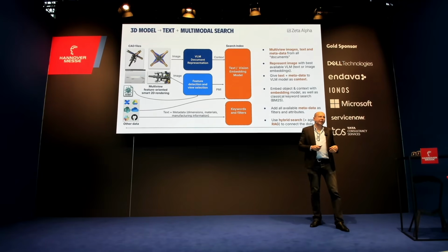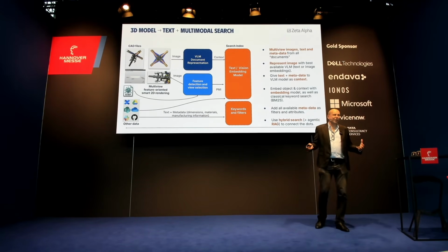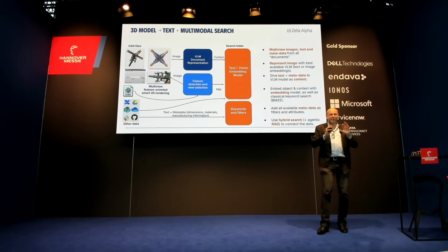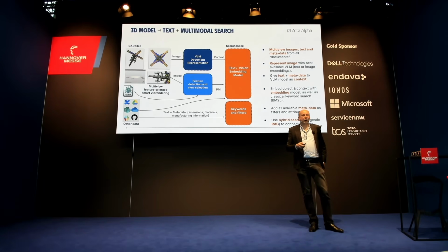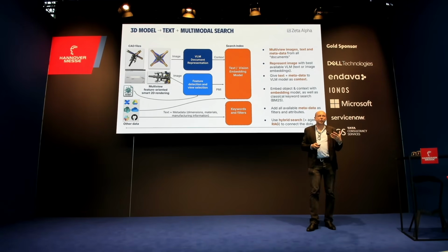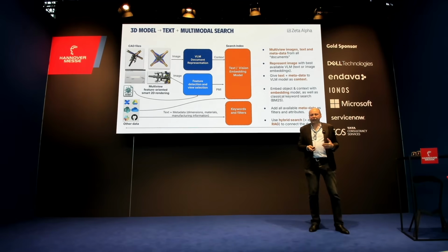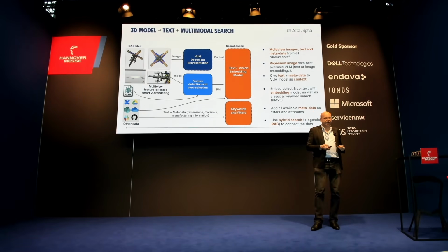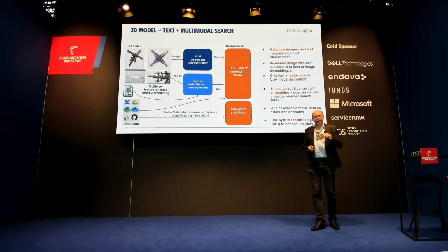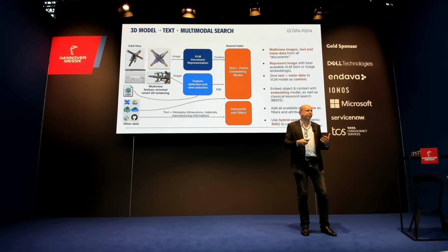And then you end up with a kind of photo album of the whole CAD model from different scales and different perspectives. That is then fed into a classical VLM where the rest of the metadata functions as context, and you're able to derive a semantically meaningful representation that captures the shape, but also the other metadata and functional information in the document. And then you can use that as filters on your search and define all kinds of hybrid search processes and AI agents on top of that.